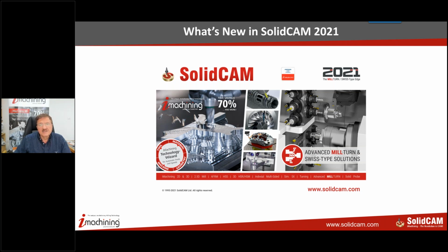In what scenarios would you need to use the ShopFloor Editor? Let's say the machine operator is working in a different shift from the CAM programmer, and the CAM programmer is not available to make any changes, so the machine operator can make minor changes and regenerate the G-code. Or maybe the CAM programmer is relatively new to machining and has less experience than the machine operator.